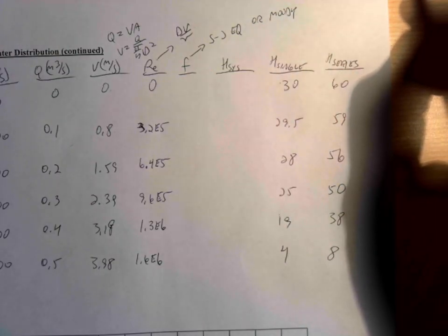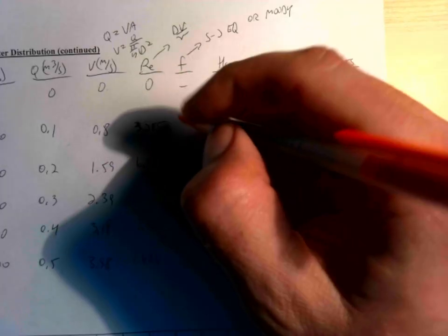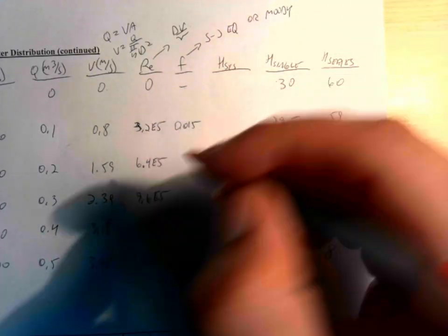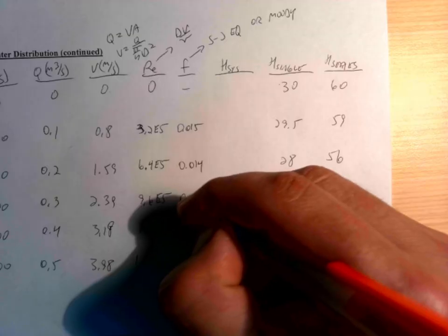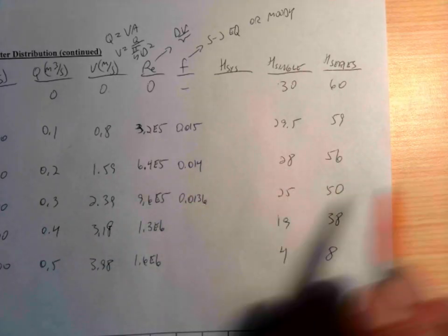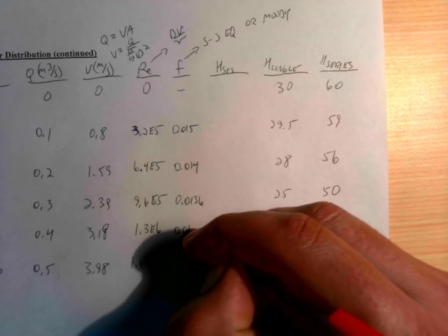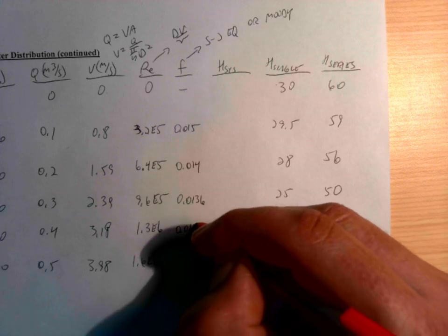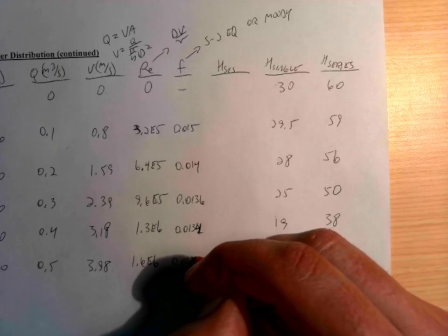So I got here, let's see. The friction factor is kind of undefined for a zero flow rate. And then we get 0.015 and then 0.014. You can see that these stop changing after a bit, because if you look at the Moody chart, the Reynolds number becomes unimportant. As you go to higher and higher Reynolds numbers, these values all become the same, but we're almost there on this one. 0.013, sorry, this is 0.0134, and then 0.0132 in the last one.